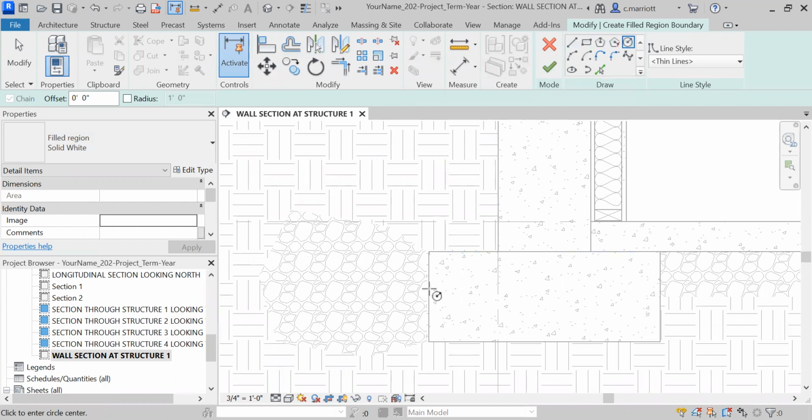You can try to center it, but again, we're just trying to get approximately this location. We're going to make a 4-inch drain pipe, but that's the interior dimension. I want the thickness of the walls to be 1/4 of an inch. So I'm going to put the radius 2.25, including that thickness, and click on OK.